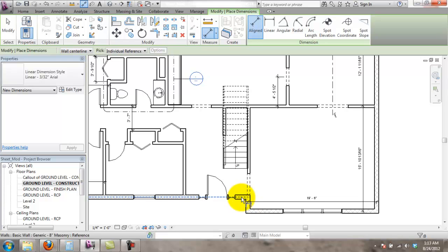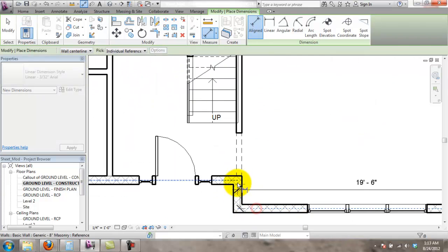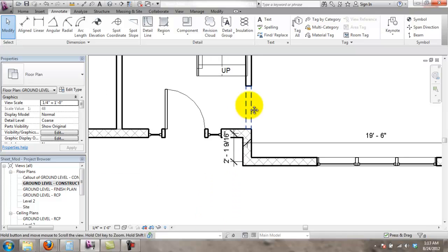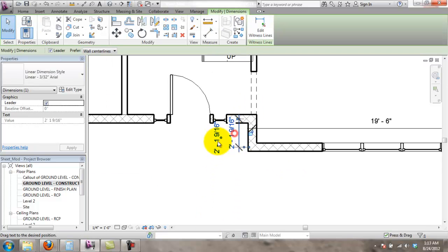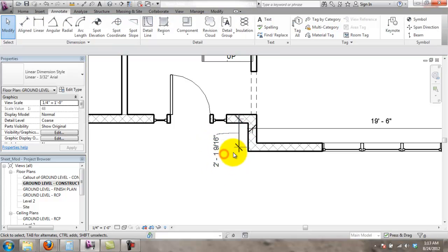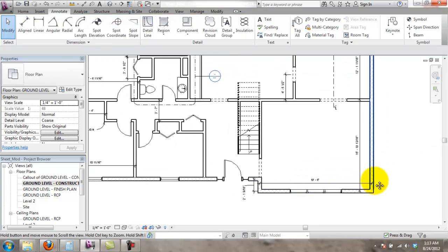I mean, it's pretty much already going to be built. What I mean is, should I dimension this dimension from down here to here? And that would be obviously no. You would probably make things simpler, and you could put it outside here. I could put it here. Now this is a major no-no. So what you'll do is you'll take this out to here, and you can see a leader is automatically put there for you. So you can put something out there like that.